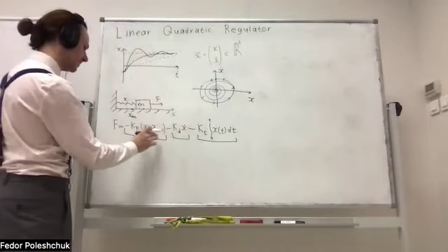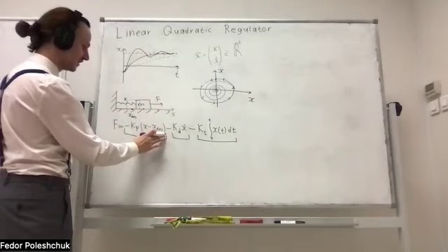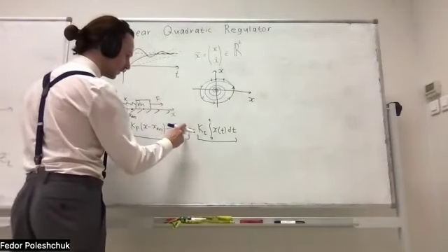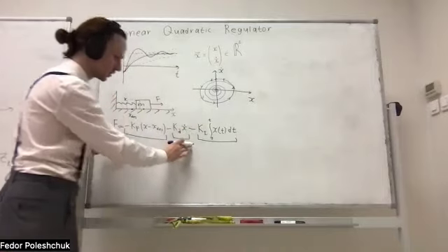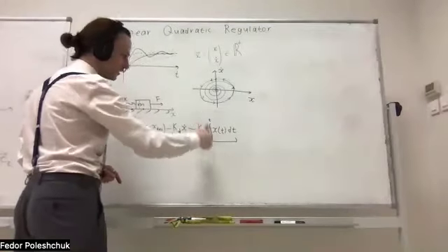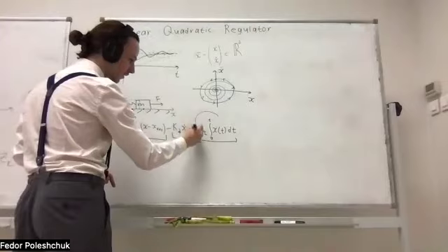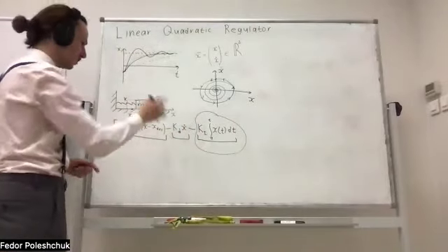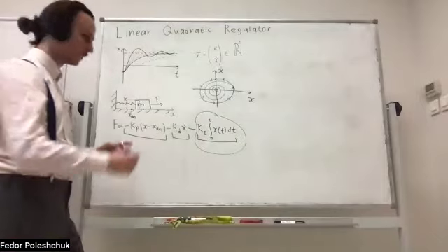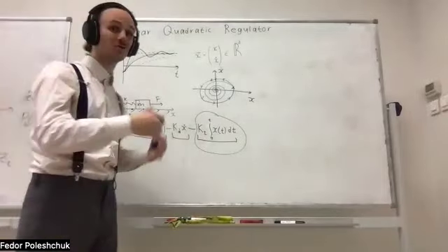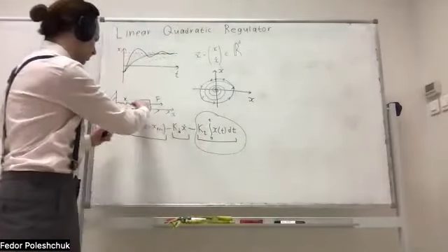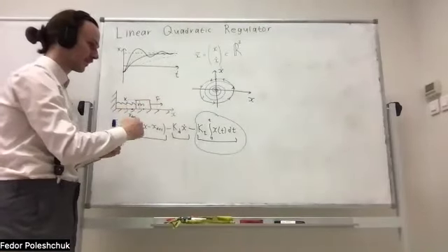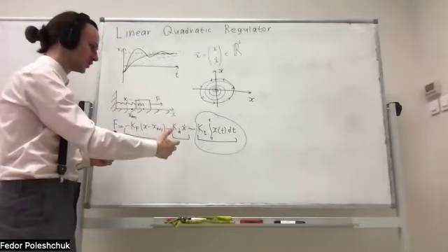So the deviation from the desired position is zero. The first term is zero. The velocity is zero, so the second term is zero as well. And if we don't have the last term, the force with which our controller will act upon the block is zero. So we really have to hold this block because the spring is compressed, but we're not doing that. So how could we approach this problem?